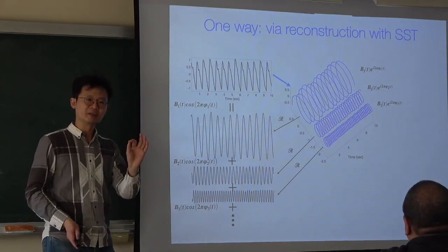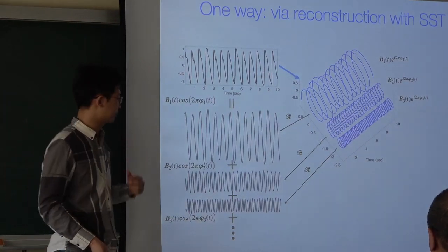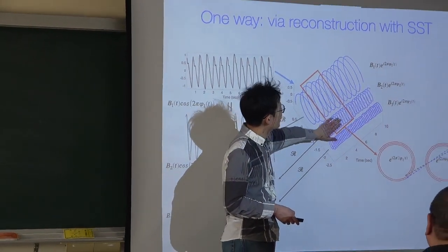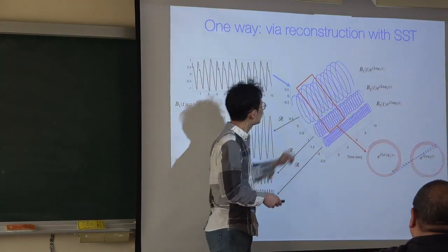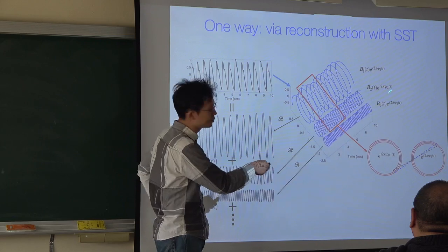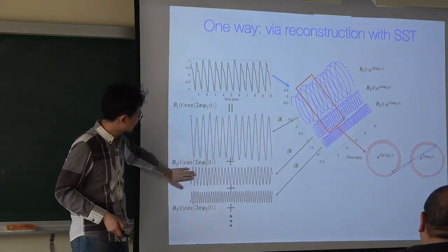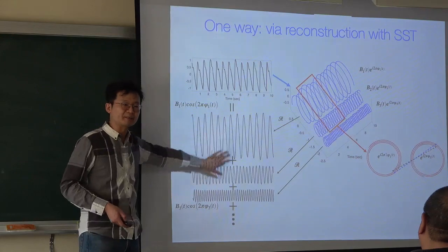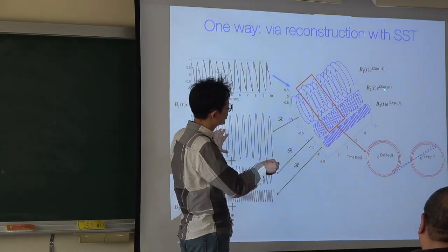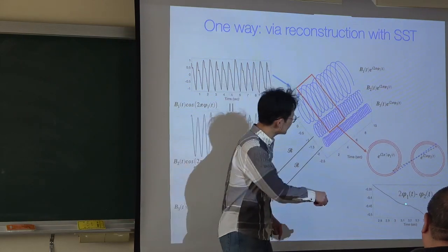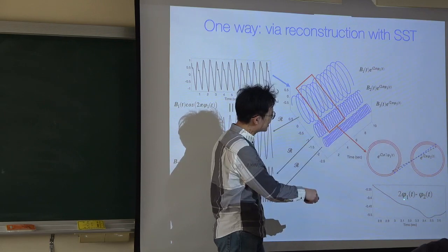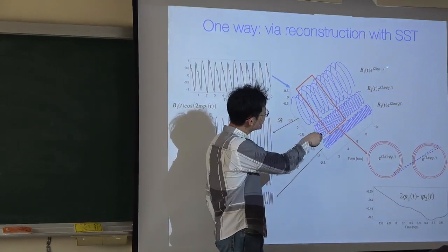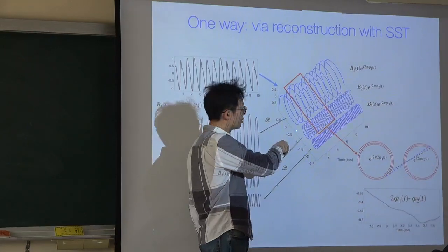But now let's take a look at what I meant by coupling. Look at the fundamental component and the second harmonic, the first and second harmonics. You can see that phi1 and phi2 obviously are not on the same order, because the second harmonic obviously oscillates faster than the first harmonic, right? But if you recall the definition of the adaptive non-harmonic model, they actually have some relationship. So what I do now is take phi1, the phase of the fundamental component, and multiply it by 2. That is, I double the frequency of the fundamental component so that it is on the same order as the second harmonic. And I do the subtraction.